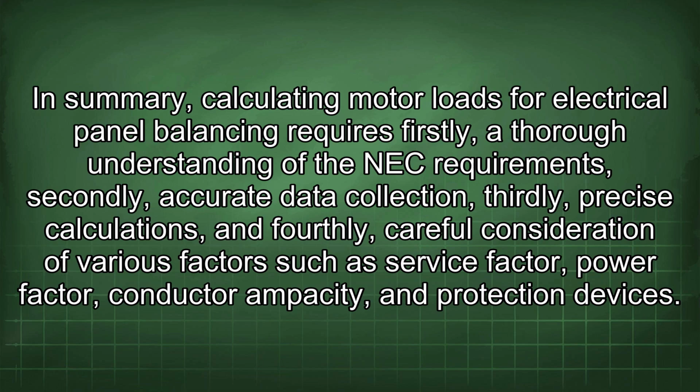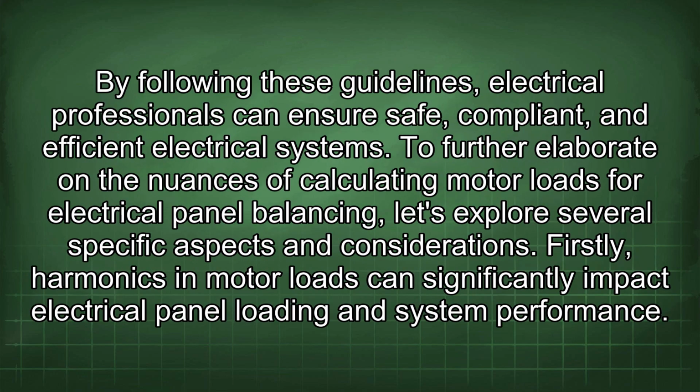In summary, calculating motor loads for electrical panel balancing requires, firstly, a thorough understanding of the NEC requirements, secondly, accurate data collection, thirdly, precise calculations, and fourthly, careful consideration of various factors such as service factor, power factor, conductor ampacity, and protection devices. By following these guidelines, electrical professionals can ensure safe, compliant, and efficient electrical systems.